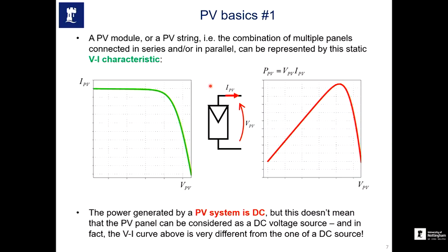Okay, so if you want more voltage out of the PV panel, what will you do? Will you connect the cells in series or in parallel? Any idea? Yeah, series, right. Because every cell will give you a certain voltage. So if you want more voltage, you connect cells in series. If you want more current, you connect cells in parallel. Same thing with the panels.